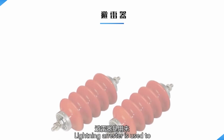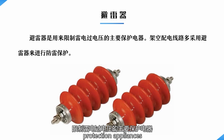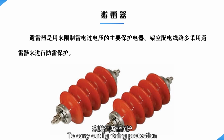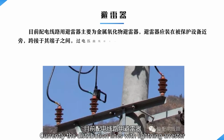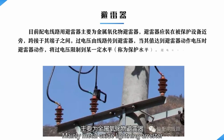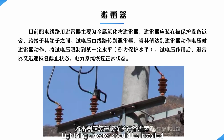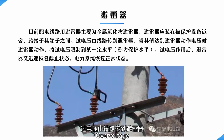The lightning arrestor is used to limit the lightning overvoltage on the main protected equipment. Overhead distribution lines often use lightning arrestors for lightning protection. Currently, distribution lines mainly use metal oxide lightning arrestors. The lightning arrestor should be installed near the protected equipment, connected across its terminals.